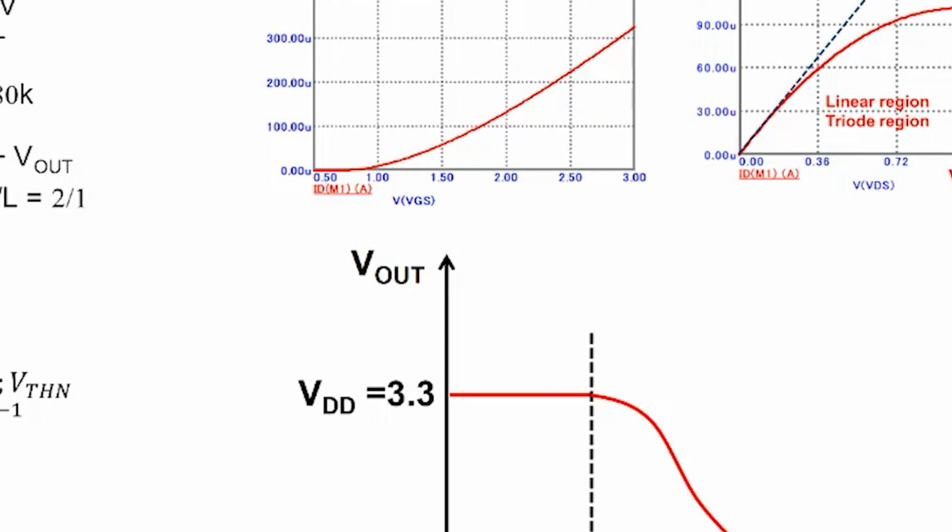So for example, if this is 1.1, VD sat for us is 1.1 minus 1, so 0.1 volt. And VD sat is 0.1, and the drop here is not that large. We can calculate how much it is. And Vout will be considerably larger. Maybe we are here, let's say Vout is 3 volt or 2.5 or so. So we start off in saturation region. But as we keep on increasing Vin, the current keeps on increasing and this voltage VDS keeps on falling. And eventually we go into linear region here, right? So we start off with saturation.